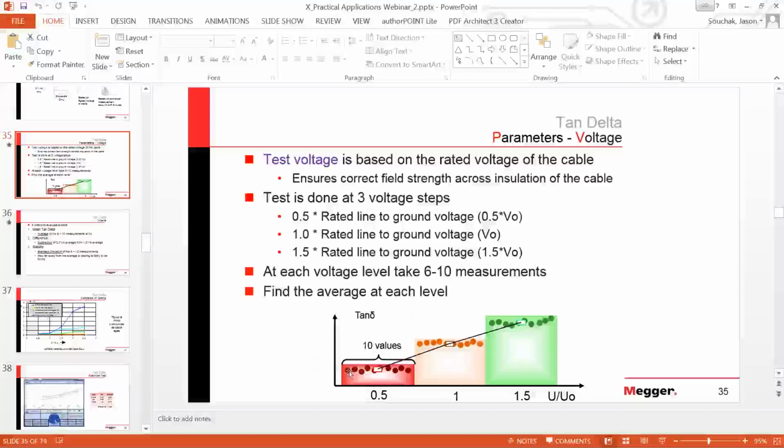We do that to get that stability measurement, really. If you took just a single point, you can't make a stability assessment off of it. But if you took multiple points, like I show here, you can see if they're stable. If you have 6 points that all come back to be the same value or very, very close, you have very good stability. If there's range there, then you have more and more poor stability. And we just simply take those measurements then and zip them down to an average. And we work with the averages as we do the assessments, really. It's just a matter of holding the voltage at that level long enough to measure 6 times, to measure once per cycle.